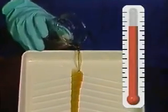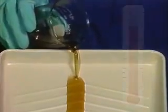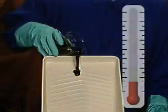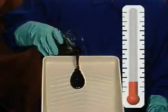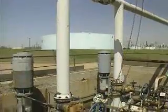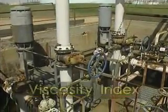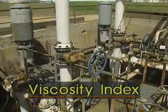Higher temperatures cause lower viscosity because lubricants thin as temperature increases. On the other hand, lubricants thicken as temperature decreases. Both cases are significant because a lubricant won't lubricate properly if it's either too thick or too thin. If a lubricant is used where large changes in temperature occur, the lubricant's viscosity index is important.